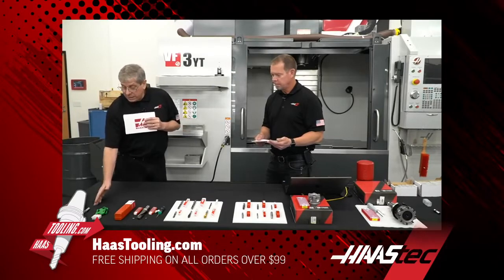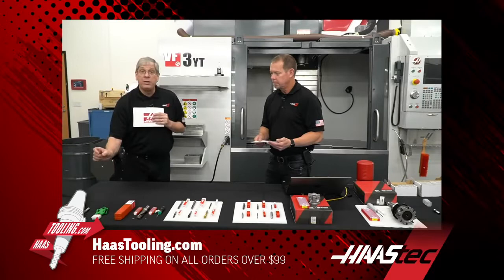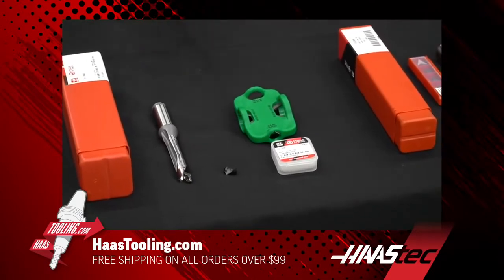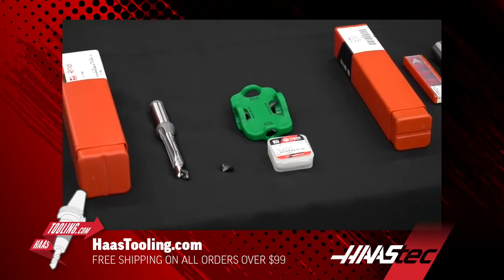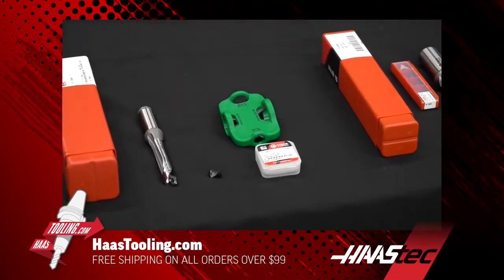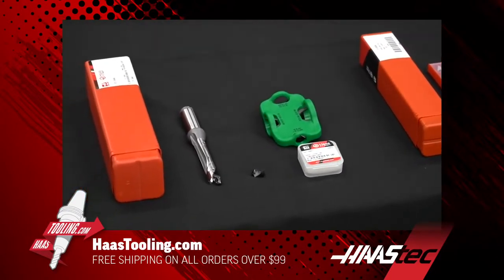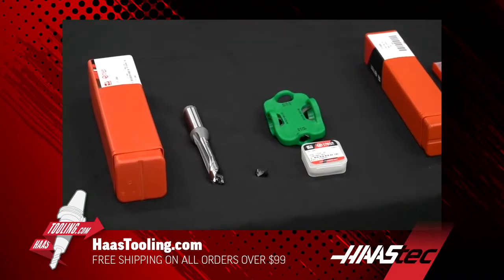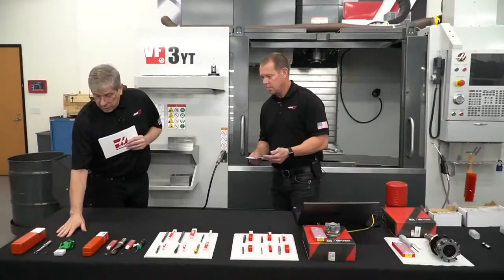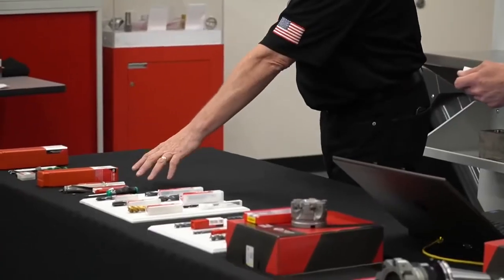And the cool thing about these is that you can get one drill body and put in a couple of different insert sizes, so you can drill different size holes with the same body just by changing the carbide insert. We have 8 different bodies, and 18 different inserts available that fit those. So that gives you an idea of how many different inserts are for the different bodies. So that's modular drilling.